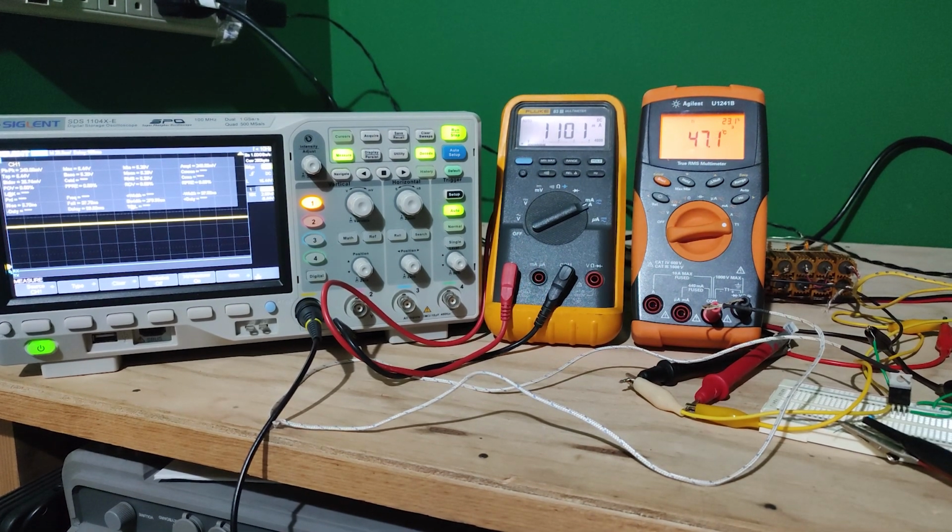And now we're going to test the same conditions, but now with linear control, which is a linear voltage applied to the base of the transistor. As we can see, we already have a higher temperature of operation. We are going to lower the current flowing through the transistor. As we can see, we are right now at 1 amp, but we are going lower. And as we go lower, we can see that the temperature is rising.